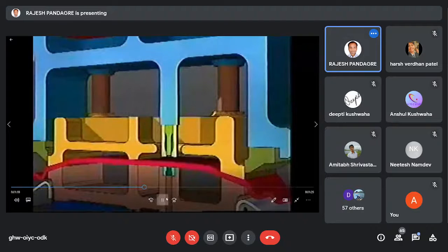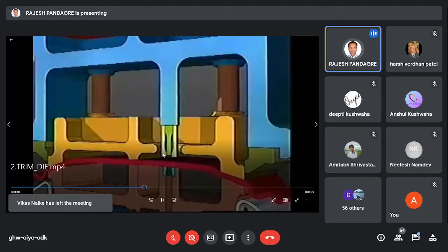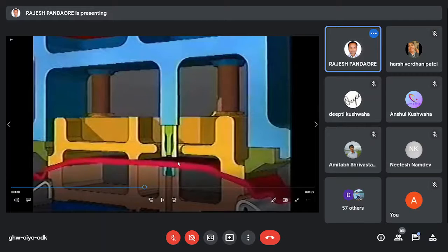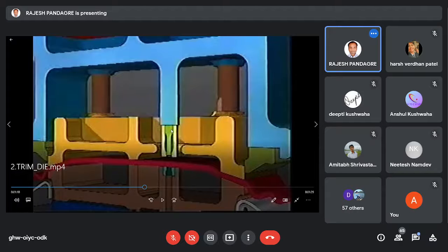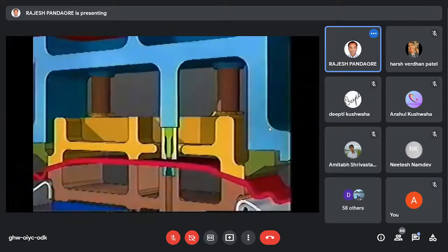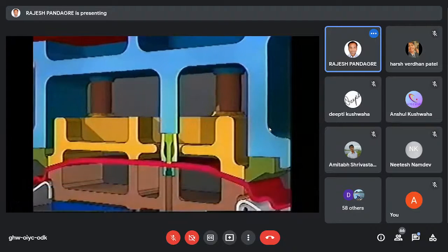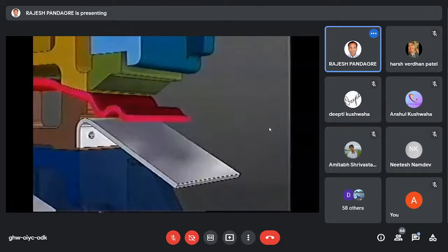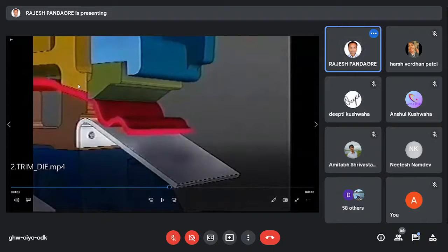The tool came, and you see these two white things; opposite to them there will be another two things. These are holding up the material, so that when we trim it, the material should not flow inside. Otherwise, our shape will get damaged. So we have to hold it properly. That is called hard touching. We are touching this hard and trimming into it. This is held properly. Here also, the trimming operation, a scissor kind of operation, is happening, so we have to hold this properly.